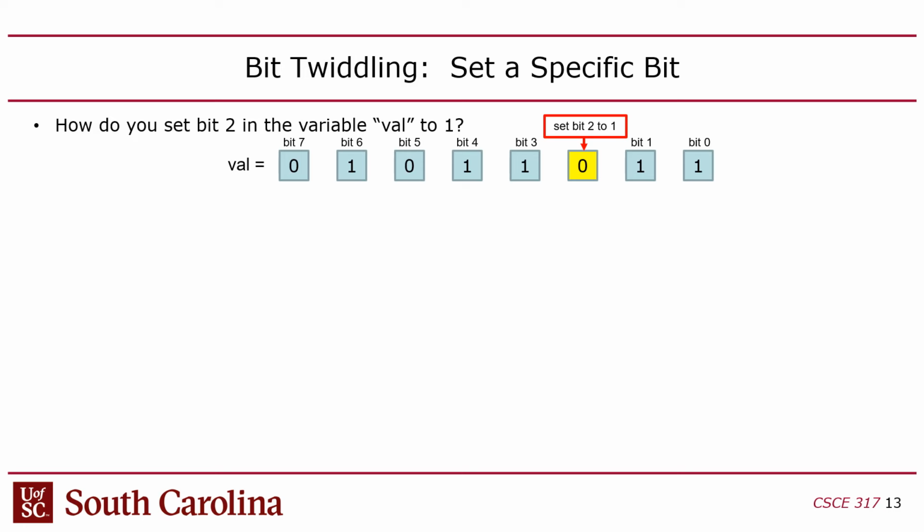The point of this is you have to go through several steps to do things like extract a bit field from the middle of a register or to set a bit field in the middle of the register. And whenever you do programmed I/O, you do a lot of that because control and status registers are usually divvied up into bit fields where you have to grab and set those bit fields. Make sense? Okay.